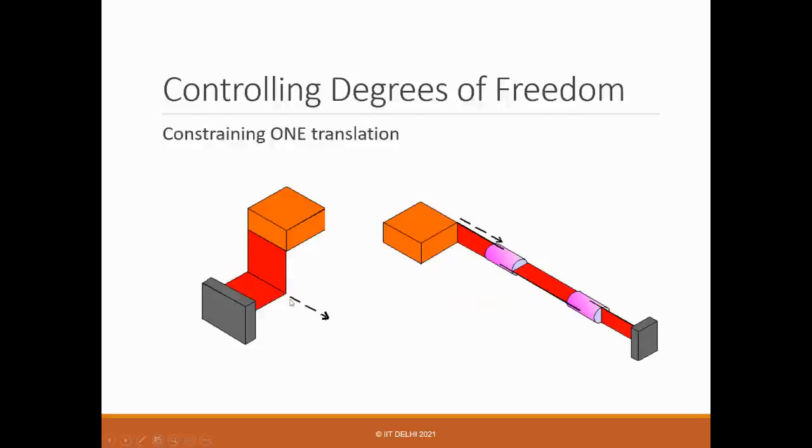So here is a folded one. So there is a sharp bend, and that's the requirement. It works only if the bend is very sharp. If it's gradual, it may not work. So in this case, if it's sharp, if it's folded, then you will also get one translation constraint along the fold line, along the folding line. Very important to remember, and we will come to that.